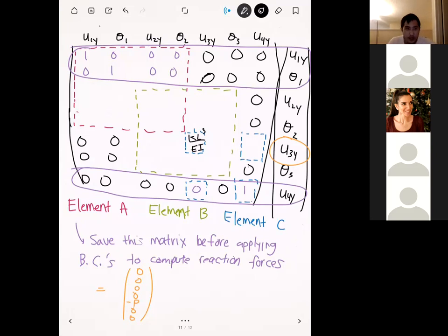And so this will basically cancel out with that coefficient out in front, and then you end up with just K. Another way to get around this is to simply plug in all the numbers ahead of time. If you have numerical representations of the element stiffness matrices, then you don't have to worry about fussing with the symbols, because all of it will be in numbers already. So that's actually what I would recommend for these ones: just do the calculations first, get everything in numbers, and then plug those into the matrix directly. Okay, thank you.